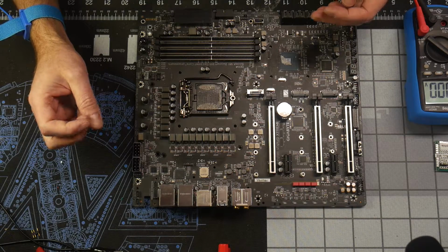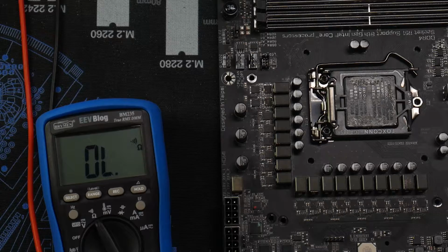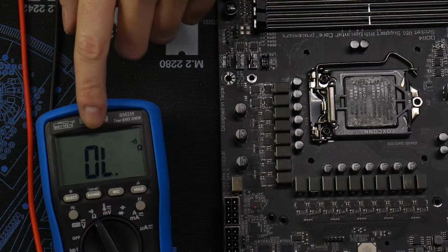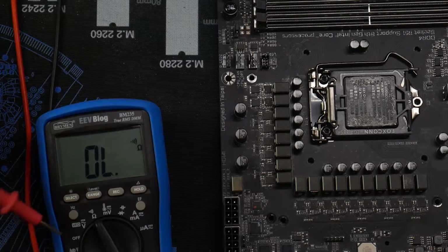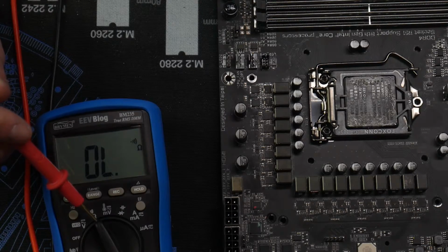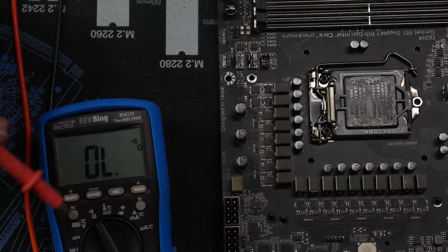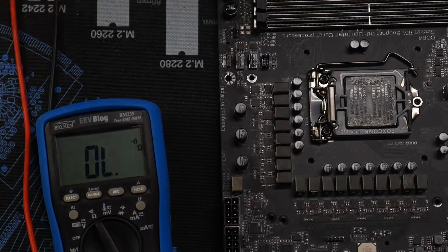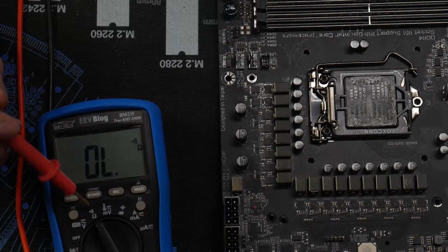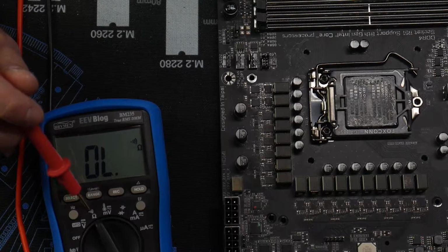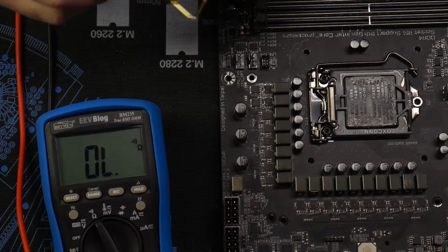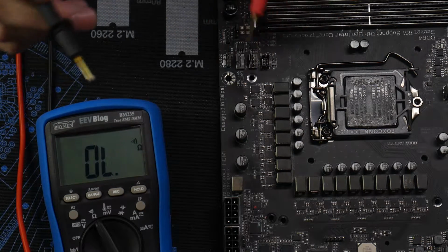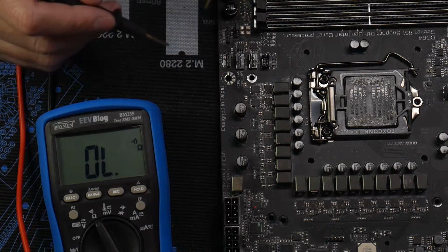Then after that we have to look into voltages, see what type of voltages it uses, and so I guess we can begin. So right here I have a multimeter, and I'm going to use this as a tool to figure out what is what. I did a little video on how to use a multimeter for LEDs, and you can check that out right here. We have it set to continuity, which is this little speaker or Wi-Fi signal right there. When I press the little leads together, it makes a little beep noise. And that's how we figure out what's connected to what.